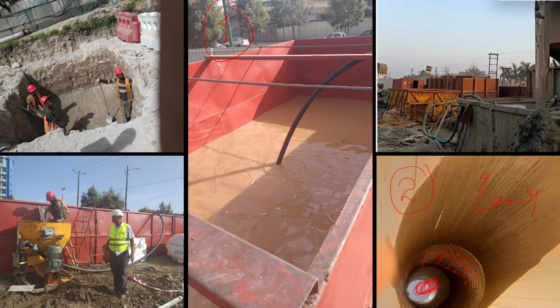We pump in the slurry chemical, and for reuse, we prepare a site excavated near the piling, this one. The slurry will be collected, pumped out, and then recycled, taken back to the stabilization unit here, so we can reuse our chemical again. Before we reuse it, we need to check the pH and also the density, and there are also other methods that we can test on site. This is very crucial and important.